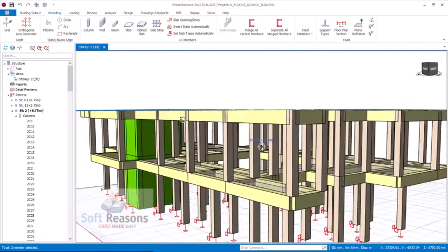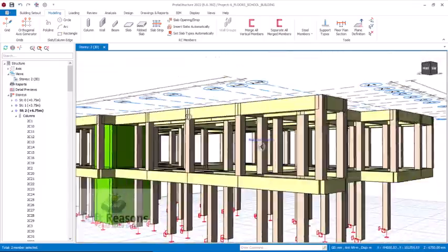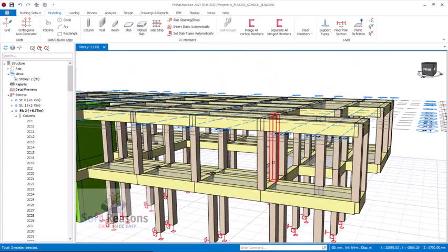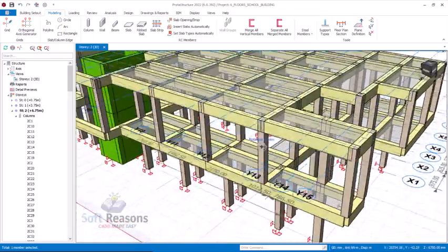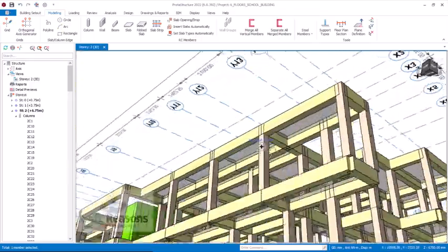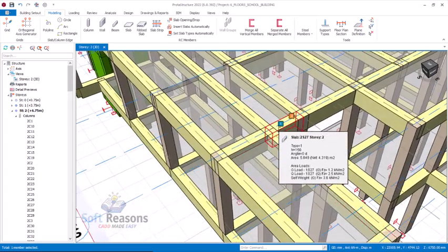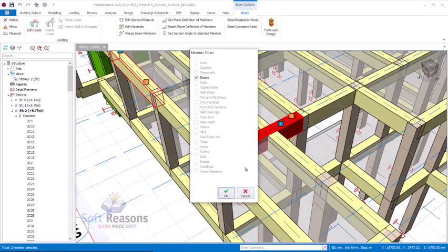Just for the provisions where we remove the reinforced concrete columns. So we are also going to remove this column as well. This one. Select this and delete it. Alright, so we have something of this kind now. Over here, select this beam, control key, select both, delete.